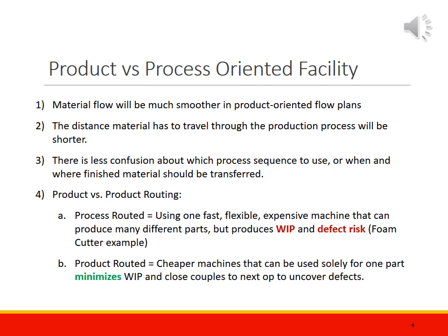Because you're in a job shop environment, you're going to have a setup. You're going to run this lot through maybe a 5-axis machine, and then the parts are going to come off the 5-axis machine, and they're going to go out to an anodized operation. And they're going to come back from an anodized operation. They're going to go back into another 5-axis machine. Right? Each time you do that, it leaves the facility. It comes back for another anodizing and machining step.